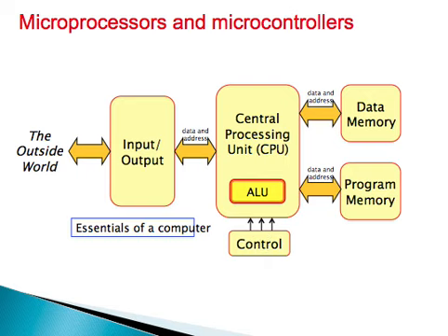On top of it, it's got to have some data memory. For example, you've got RAM or ROM. RAM is random access memory and ROM is read-only memory, which is where your program could go. However, in the new technology, instead of read-only memory, they use flash technology, so you can program it and reprogram it. So this is basically the core of a microprocessor and a microcontroller of an embedded system.